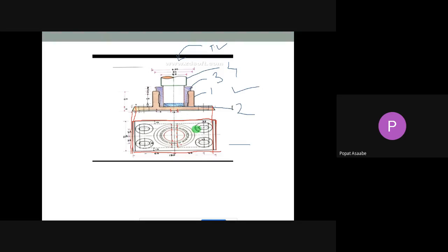See here, from the top view, the diameter of that shaft we can easily observe, so first you have to draw the diameter of that shaft. Okay, whatever diameter they have given, according to that draw this circle here, it is visible. Again see here, these two circles, circle number 1 and circle number 2 here, these are visible.